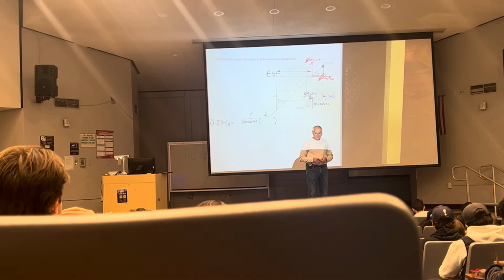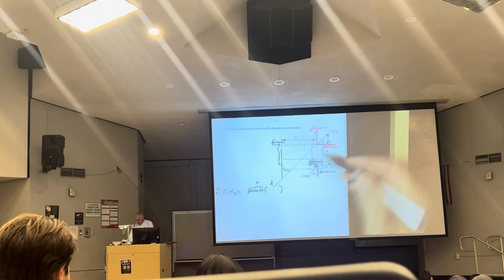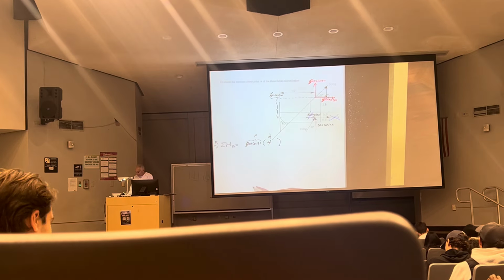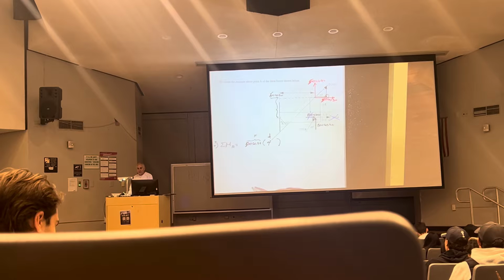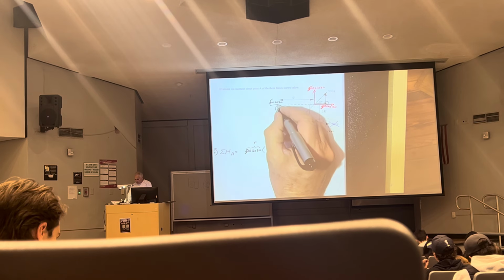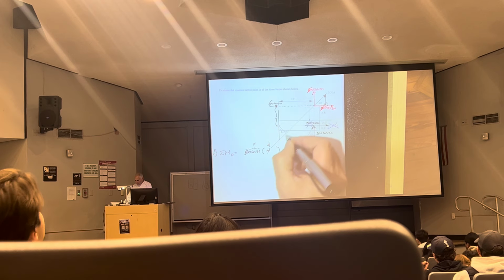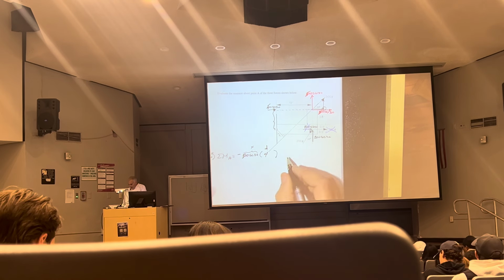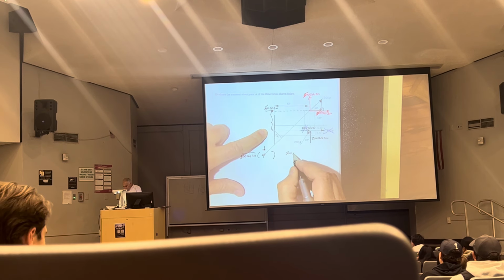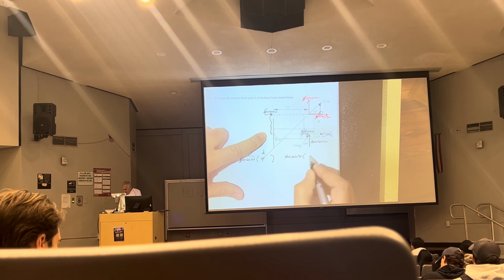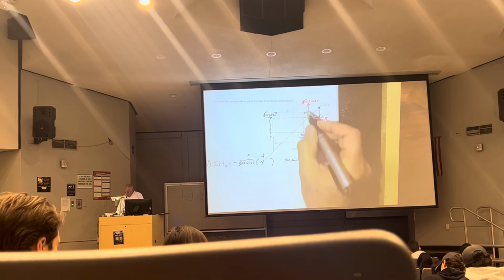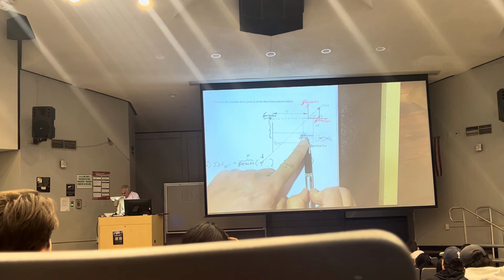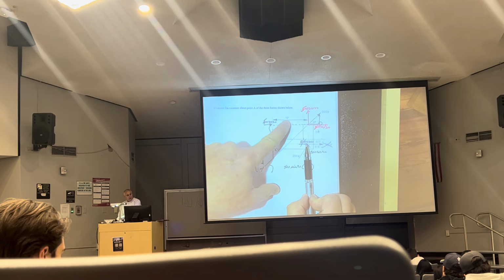Well, that distance is 3.5 plus 0.5. That's cuatro. 4 for you non-Spanish speaking people. Now, tell me, clockwise or counterclockwise, take the arrow and your pen and go around A. What is that? That's a big old negative on that one. Then I'm going to do 500 sine 30 times its distance. Well, if I move this all the way down to here, its distance from here to here is 12.